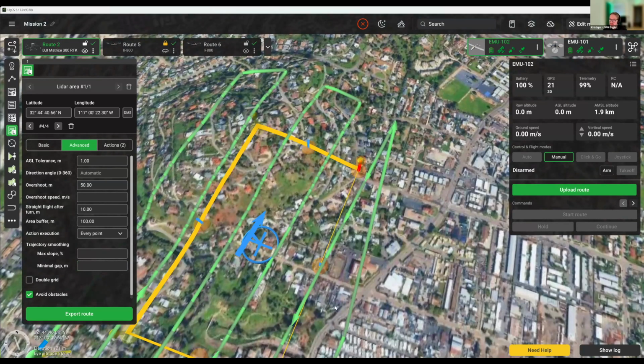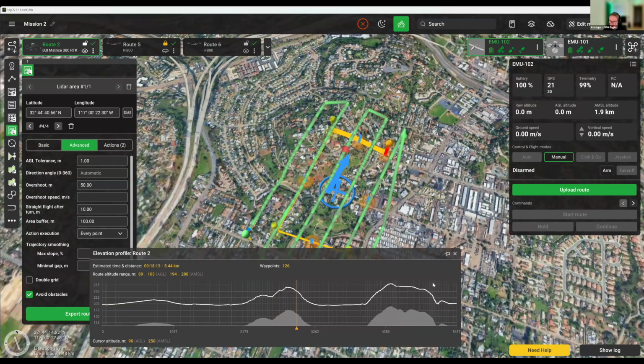Now this is at a 90 meter altitude, as you can see here. So there's no real restriction. There is a maximum altitude of 120 meters in the drone's profile, but this you can change. In case you even need to fly at 120 or 130 meters, I suppose in feet that's above 400 feet, if you have the permission to do so, then you can also configure this. I know some customers of ours who are flying drones for mining, over large mining quarries, and they have the permit to fly higher than the normal legal altitude, because of course that's their specific location. So in case you need to fly higher, UGCS does allow you to do so.